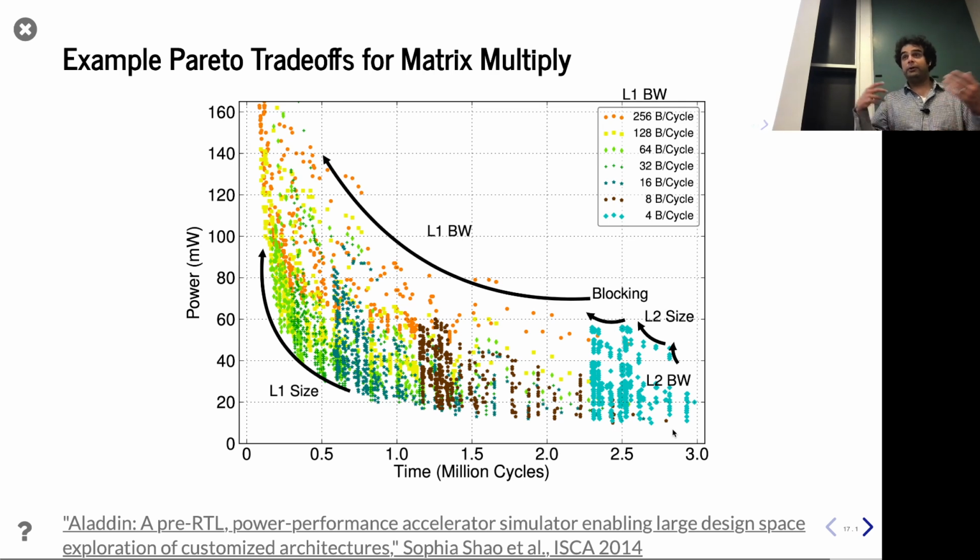So you see, this is why you have design exploration. You really want to see what are all the possibilities, what are all the options, what are all the parameters, and explore this. And so if you're only doing like two or three design points, you aren't getting this, right? You aren't learning how close you are to the edges. You aren't knowing what the limits are, how much you can push it, right? And so you really want to have a lot of design points in your exploration to figure this out.